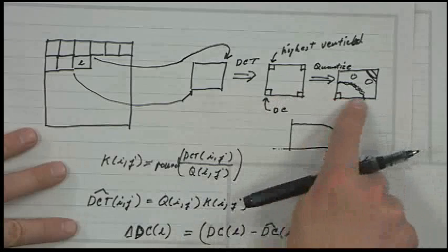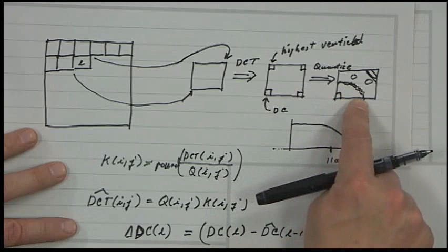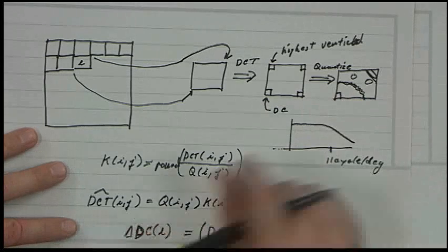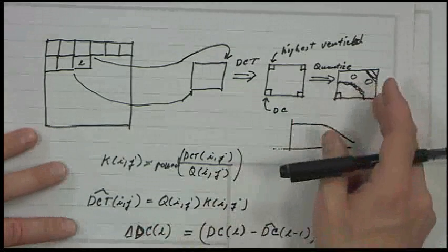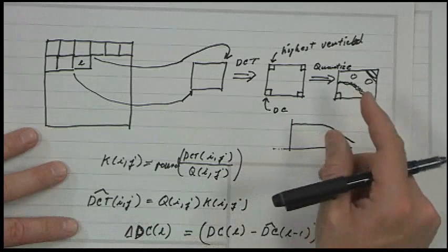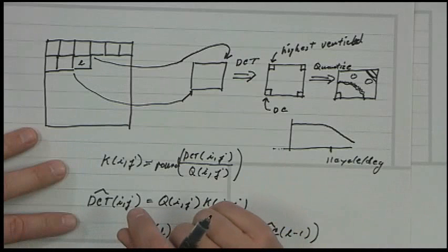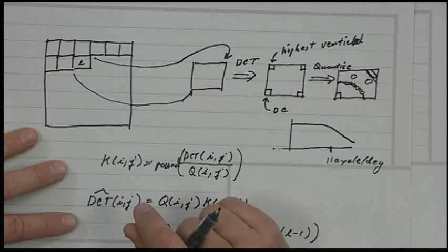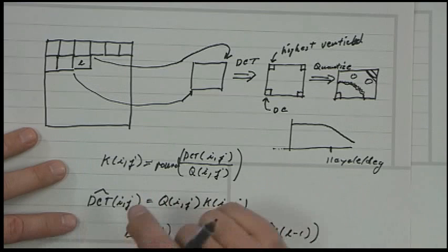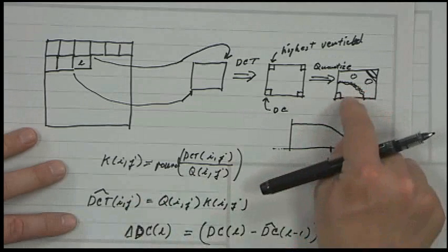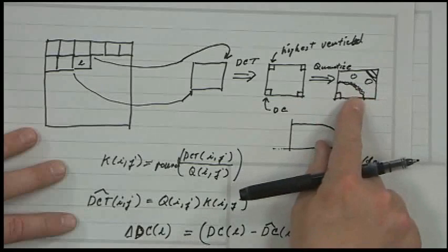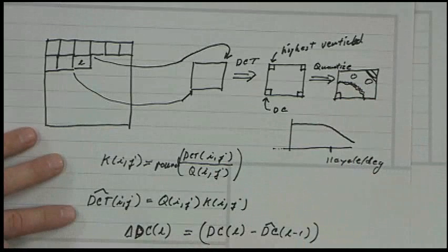For the AC coefficients, it's not worth doing that. There's not enough redundancy to make it worthwhile. Those you just quantize individually. Then after you do the run length coding, there's this VLI, VLC stuff, which I won't even try to explain, but you can read about it. It's variable length, the number of coefficients in each of the quantized values. Then you do Huffman coding of that information, and you send it on its way. And the decoder reverses all this.